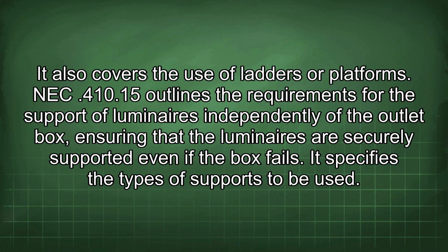NEC 410.15 outlines the requirements for the support of luminaires independently of the outlet box, ensuring that the luminaires are securely supported even if the box fails. It specifies the types of supports to be used.